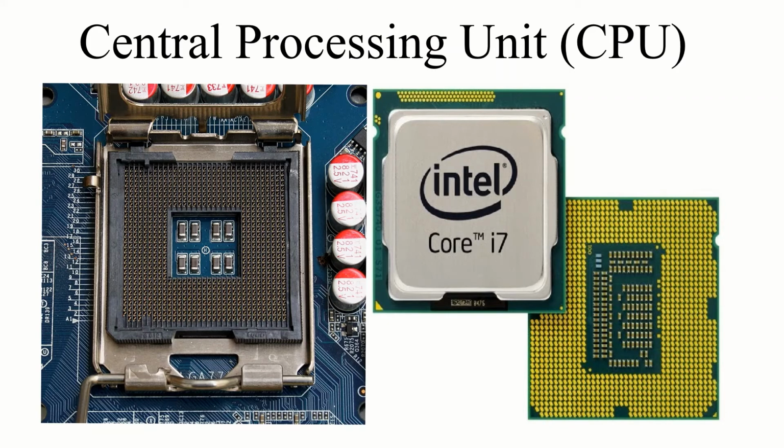Sorry, come back. Yeah, in this picture, we can see the processor slot and processor, and we need to put the processor on the motherboard in the correct position. Otherwise, the processor or the motherboard could be damaged. Here on the processor, you can see the arrow mark. See this arrow mark in this area and this area, and a cut shape in the processor slot. So we can put the processor this way.